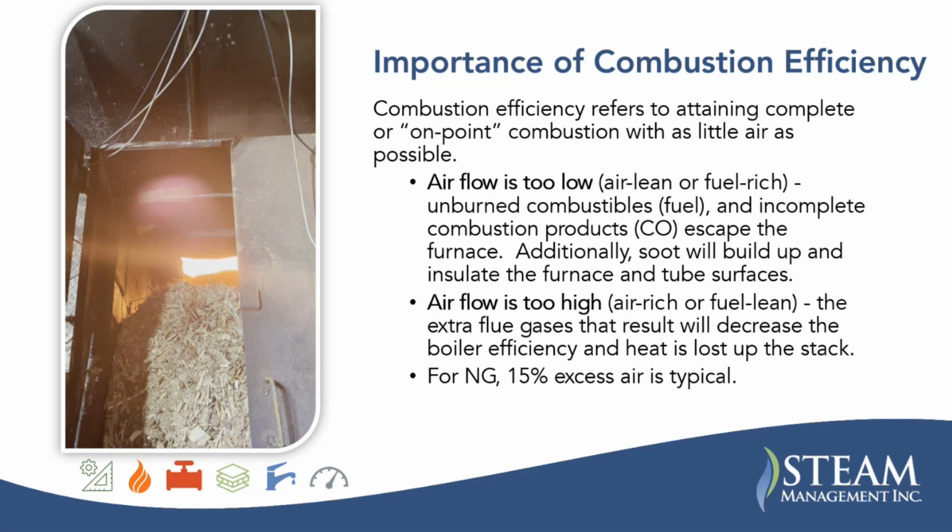There are two conditions that fall outside of the ideal operating point. The first is when airflow is too low, which is called air lean or fuel rich. In that case, you get unburned combustibles and incomplete combustion products like carbon monoxide, and those escape the furnace, which is lost heat. Additionally, you'll get soot buildup in the furnace, which will insulate the furnace walls and tube surfaces, reducing your heat transfer.